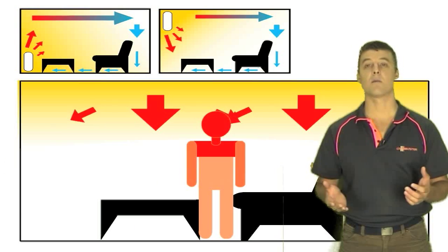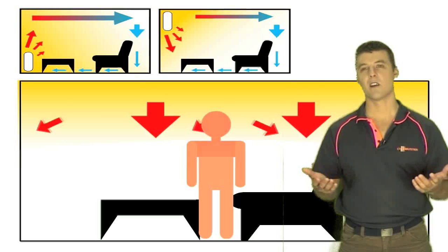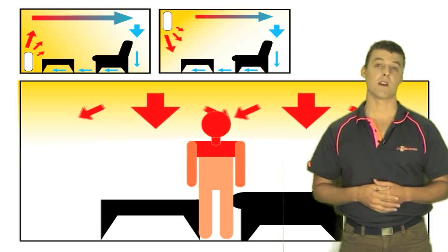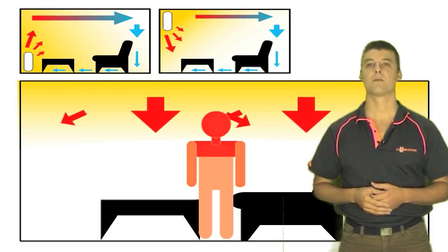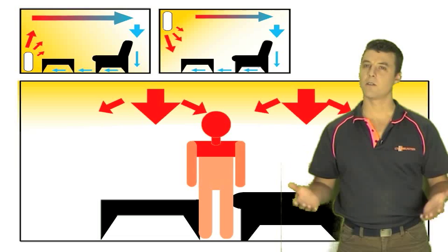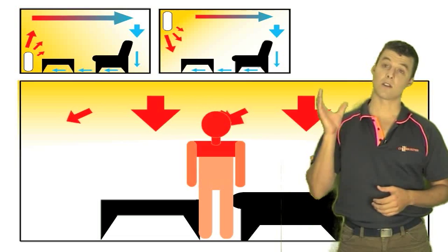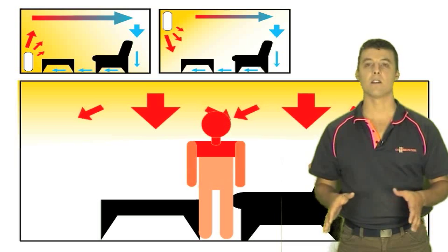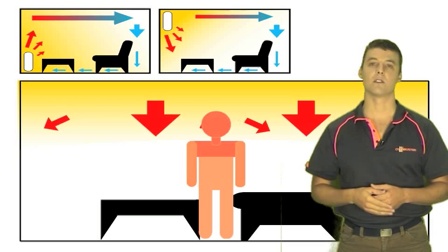Radiant ceiling lamps are mainly found in bathrooms and are not suitable for heating larger areas, having a double disadvantage. Firstly, radiant heat is concentrated around the source. Secondly, heat naturally rises, and being mounted on the ceiling, heat lamps use more energy to force heat down to warm the head and the shoulders.